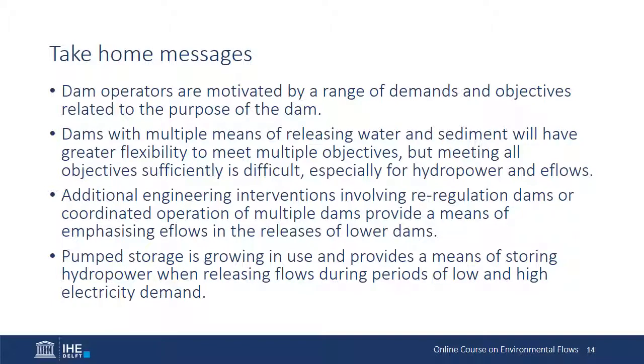Additional engineering interventions involving re-regulation dams or coordinated operation of multiple dams provide a means of emphasizing E-flows in the releases of lower dams, but this is also costly and may lead to reductions in power generation. And finally, pumped storage is growing in use and provides a means of storing hydropower when releasing flows during periods of low and high electricity demand. The stored water can then be used to generate additional electricity during high demand periods.